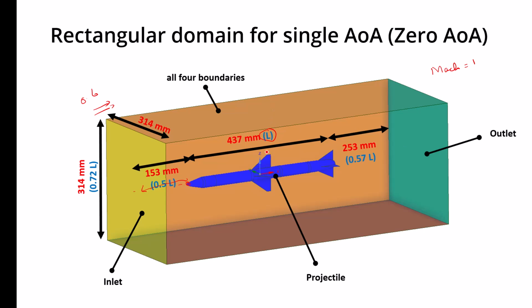Now you may ask whether it will affect the lateral boundaries. Because the geometry's length is high, but its diameter and the fins and wings are not very large, it should not be affecting there. But the problem is that there is a shock wave, and those shock waves are present here and here. The flow features will be moving like this, and they will be hitting the boundaries on the sides. So I cannot put a symmetry boundary. A symmetry boundary is very good, it does not produce any boundary layer. The problem is that the flow cannot pass through this boundary.